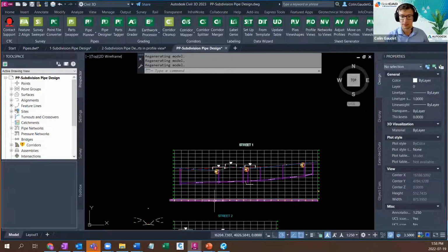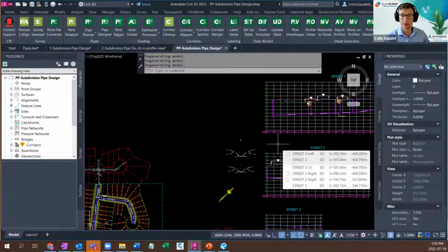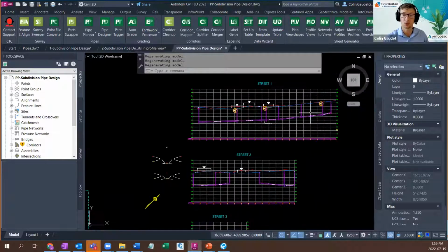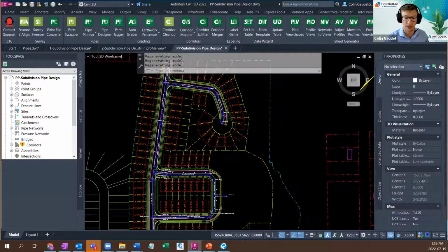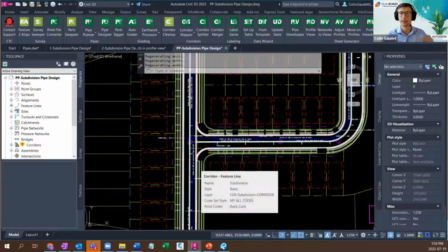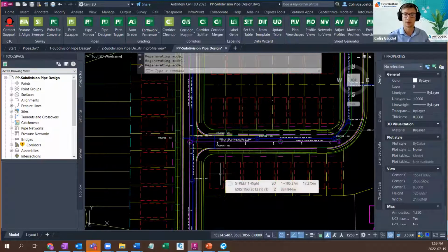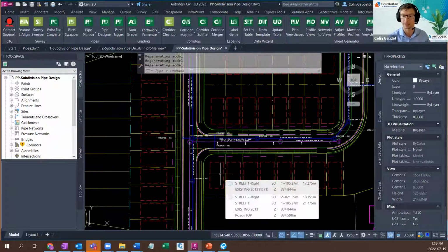Now, Pipe Designer is great. It's a really quick way within Civil 3D, the fastest way I've seen within Civil 3D to be able to design our pipe networks in a run style. Now, I like to look at it in profile view. I think that's a lot more visual for me. That being said, you can absolutely be doing this in plan view here as well. Selecting in plan view and then updating it in the interface to push it back out. It's all Civil 3D. There's nothing proprietary to it, right? It's just offering a more user-friendly interface to be able to manipulate all of our different elevations, inverts, and things like that, and slopes.